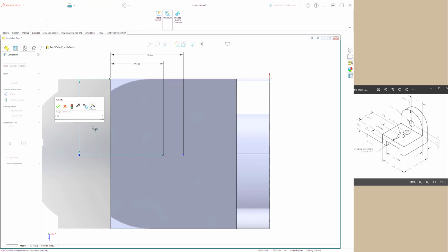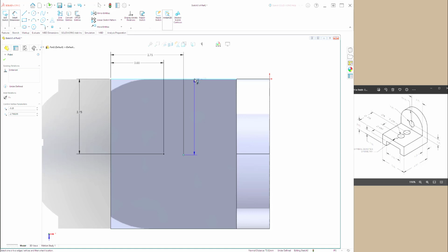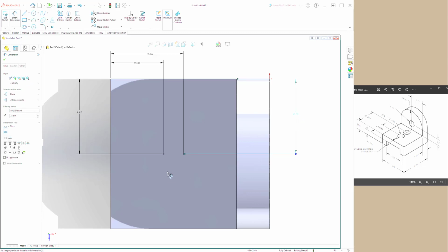How did I know that? Well, the radius value is 2.75. That created a perfect radius across the top. And the 5.50, half of that value, is 2.75. And I want to make sure that both of these points are 2.75, because not all the time do they stay aligned. So I'm going to do it to each point. All right, so now we've got our 2 points positioned and located. So again, feature size, feature position. This was all about feature position.